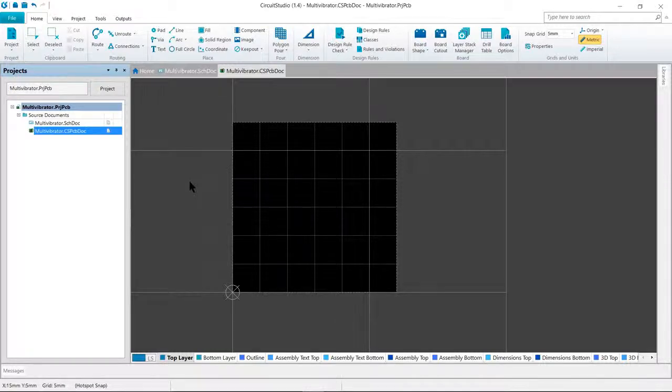There will also be a list of all nets, your connected component pins, in the design. When the ECOs are executed, the software will add each net to the PCB and then attempt to add the pins that belong to each net. If a pin cannot be added, an error will occur. This most often happens when the footprint was not found or the pads on the footprint do not map to the pins on the symbol.